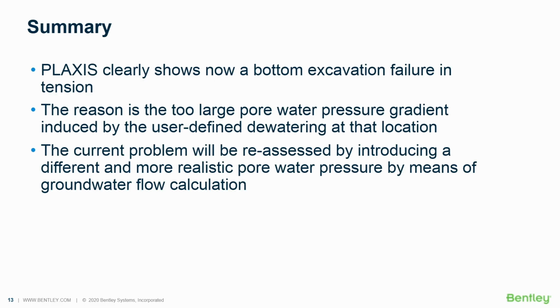Still good for you to remember the location of the inaccurate failure plastic point and tension cutoff plastic point, as well as deactivating the arc length control in order to force the failure mechanism to further develop and get a better overview of what's going on. Sometimes it's good to force failure to understand what's going on.